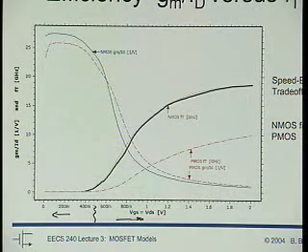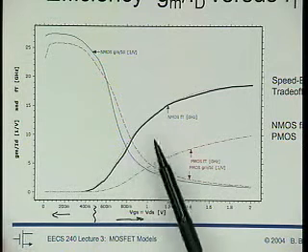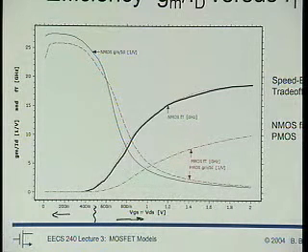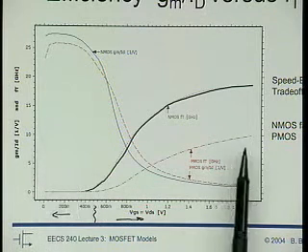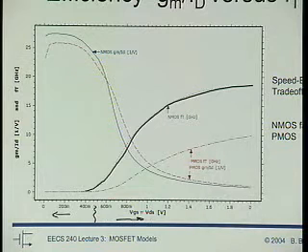We would like to run the transistor in weak inversion or close to weak inversion to get high current efficiency. Well, if we want to get high speed, apparently just the opposite is the case. Another insurance for the analog circuit designer: you can't just blindly go here or go there. You're not going to do very well with that.